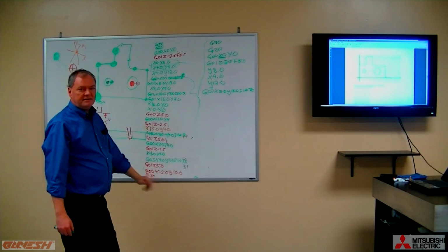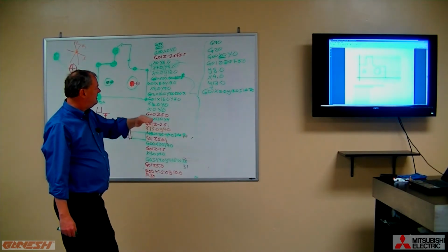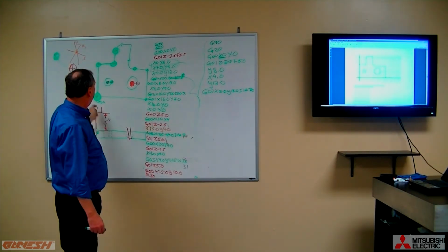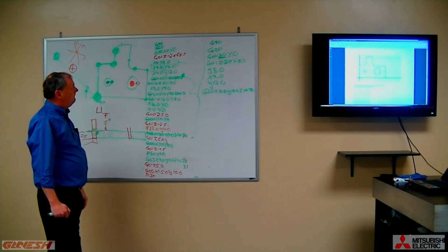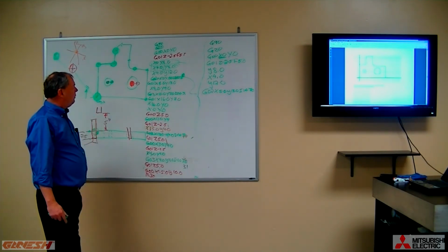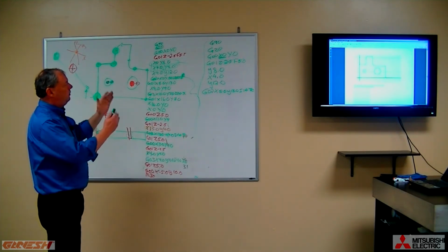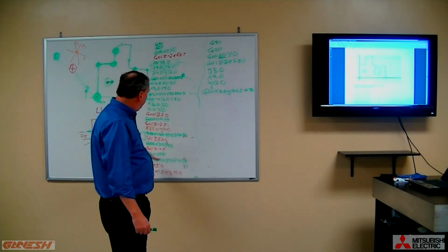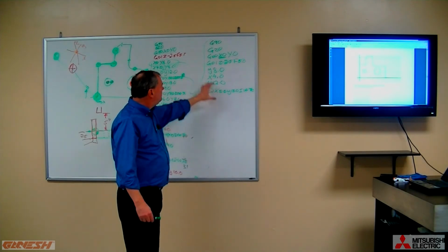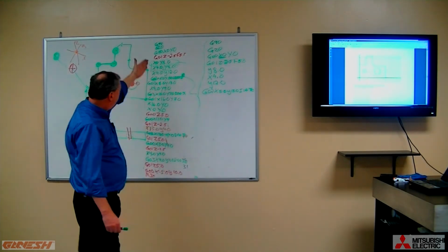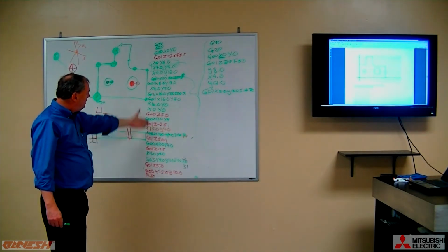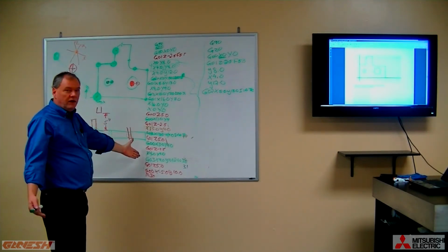has a beginning, has an end, and has Z moves so that you're not cutting through your material. So with a one tool part program, this is it. It's done. We're finished. You can transfer these blocks over into the reduced program, but for the parts that we've done here, you have a valid program.